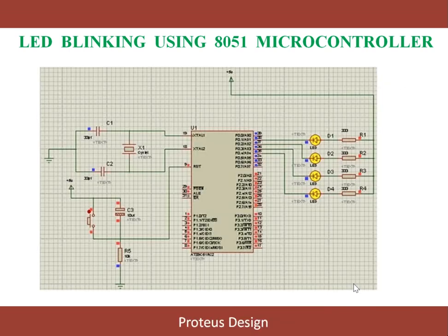And here is a prototype. On Proteus software, we can replicate the circuit. We can design our prototype here in Proteus, and for example, we have used the AT89C51 microcontroller. It gives us 4 ports to be used. It has address and data lines also, 16 address lines and 8 data lines.